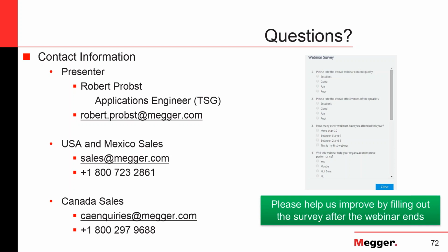I'd like to add to that in the fact that the breakers do heat, as Robert mentioned, and the standards do call for cool down time when testing adjacent phases. Therefore, it is commonly practiced to test A phase, C phase, come back to B. In addition, the other thing Robert mentioned is the control of the current while testing, while these breakers heat.